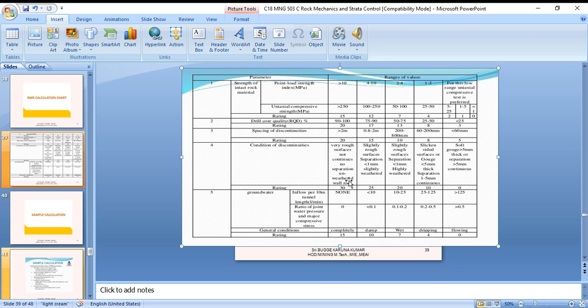So many theories also there. Theory of supporting will be simplified. The rock pressure theory was developed based on basic observations in underground excavation: development of a rupture surface beginning at the edge of the excavation, appearing as vertical cracks. He assumed the rupture failure takes place along a curved surface rather than along a plane. The profile of the surface is derived according to the following expressions.